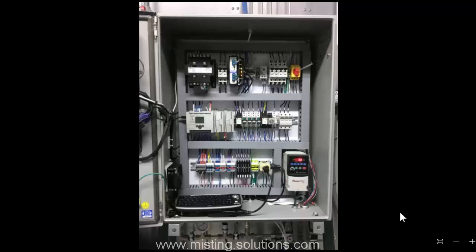Now, before I go too much further, I wanted to explain this picture a little bit and talk about the overall controls within the control panel. As you can see, we've got 3 sections here: top, middle, bottom. Top is the input-output section for power. Middle is the control section with microcontrollers, input-output relays, and timers, and then the bottom row is input-output terminal strips that go out to terminal points that go out to the controls and to the solenoids.